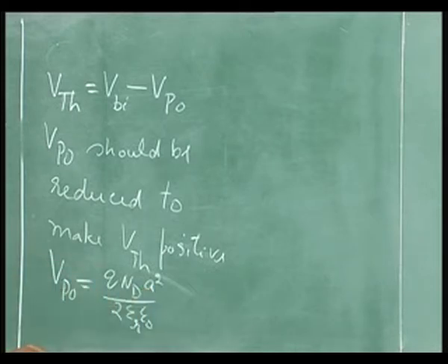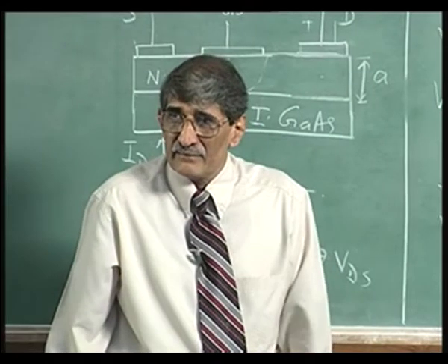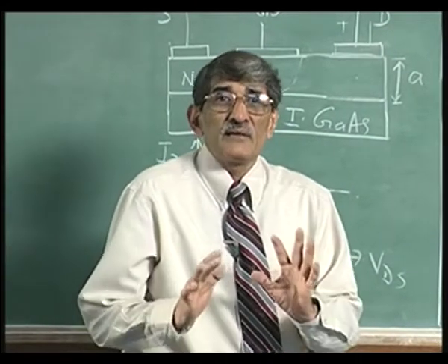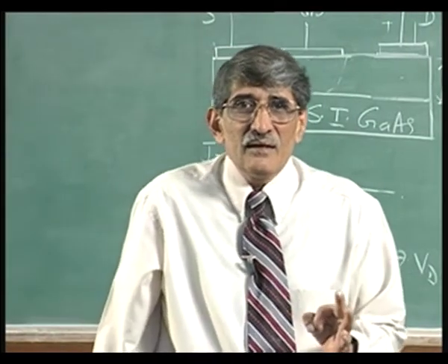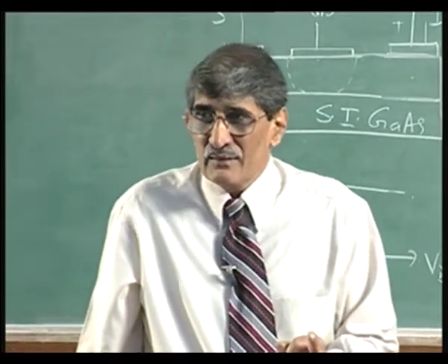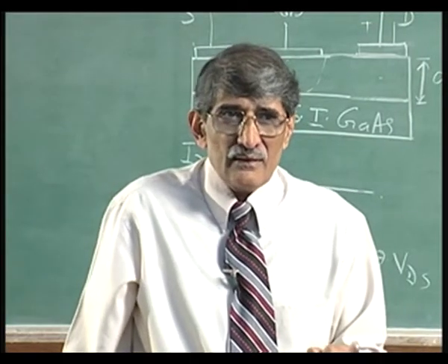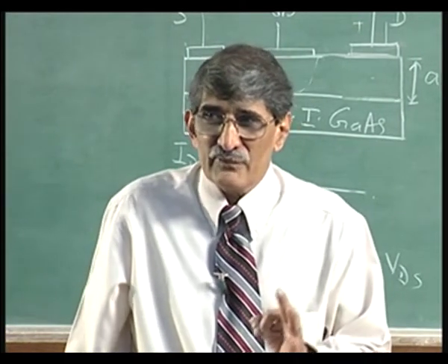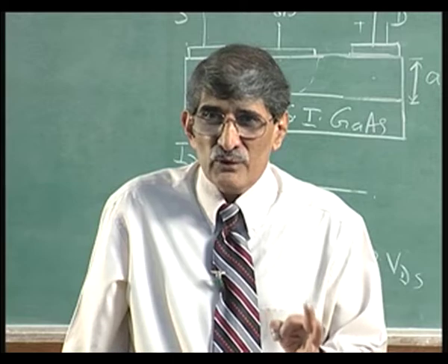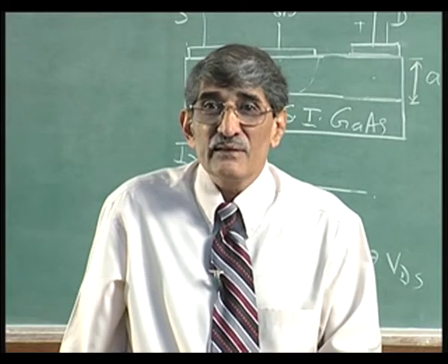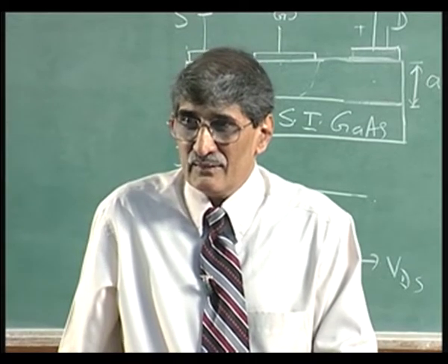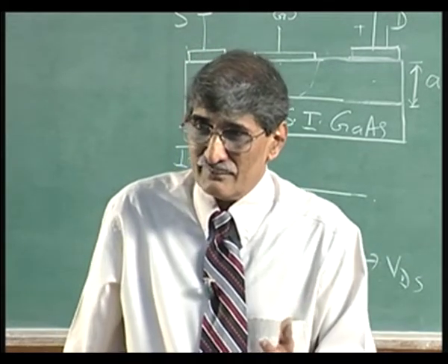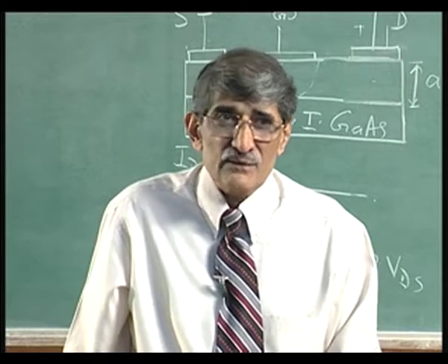If you look back, you may not worry in long channel devices much, but if you look back into the MOSFET theory, you will see the scaling laws. What you are doing is reducing the thickness of the oxide and increasing the doping to control the threshold voltage.